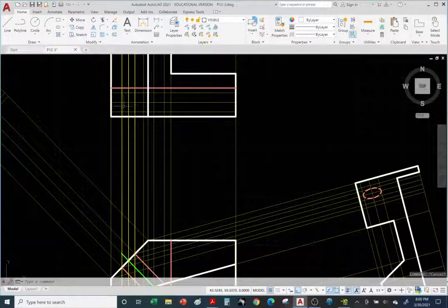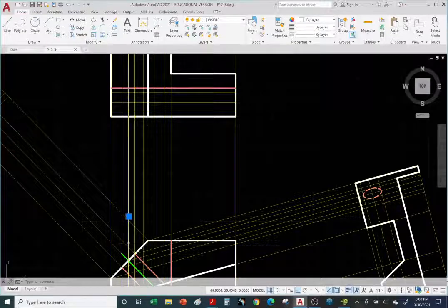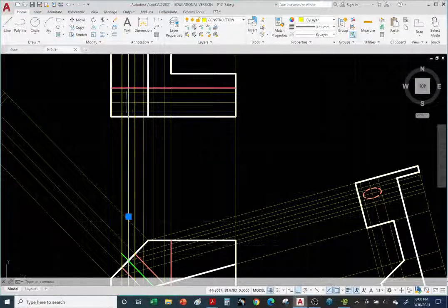So the hole is in here. We know the center line, right? There's the green center line as it exits the solid at the white visible object line. So we know this line is for the center mark. So here's the center, here's the left quadrant, right quadrant, and we already have the construction lines for the top and lower quadrant of this hole.